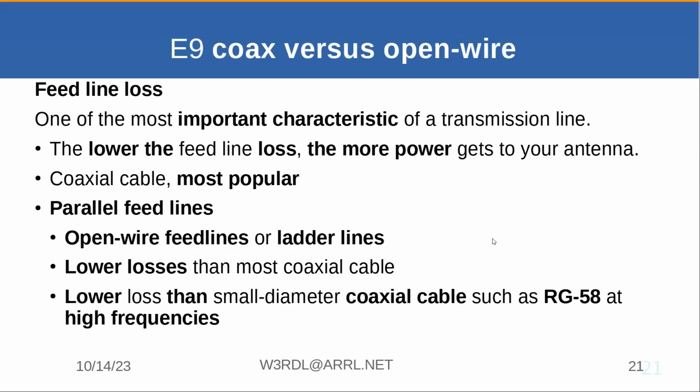It sounds reasonable that it would only be resonant at one frequency. With a regular dipole, you can resonate at the odd multiples, or evens, yeah, evens. But basically the folded dipole is a loop that's a full wavelength long.